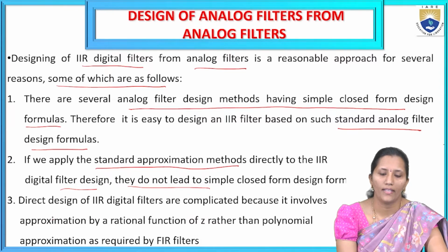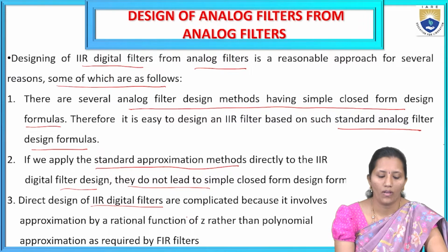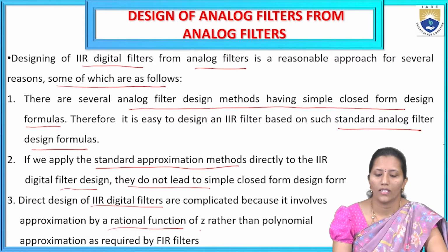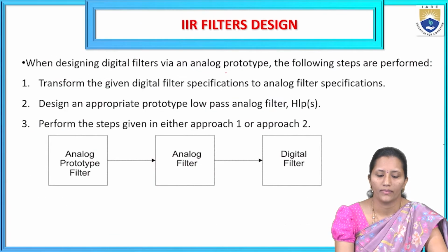Direct design of digital filters is complicated because it involves approximation by a rational function of z rather than the polynomial approximation as required by FIR filters. So these are the reasons why we are going for analog filters. We take analog filter prototypes for the IIR filters.